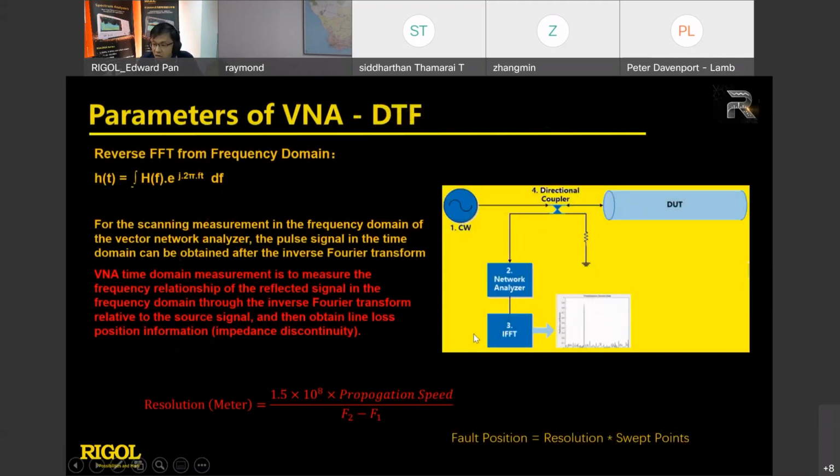It is the TDR functionality, which is very easy to understand. You send a waveform from the original position, travelling at a constant velocity, and get a reflected wave from the interrupted point. You multiply by two for the round trip, so the total distance is found by dividing by 2.